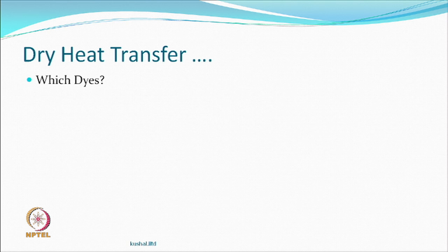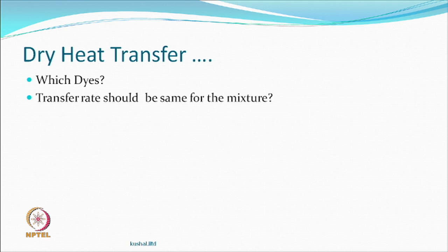Obviously, it has to be a dispersed dye. The transfer rate should be the same for the mixture. This one has to work carefully in consultation with the dye manufacturer. Dye manufacturers give you charts which have all the experiments done on the dyes, and when you try to mix them up, you should know which dye to mix, because you will be using mixtures of dyes to get different shades.